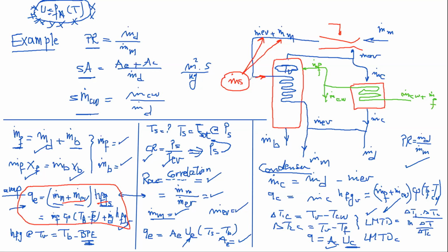It enters as saturated vapor, it leaves as saturated liquid. So the difference between them is basically HFG. Okay. Is that clear? But how do you equate it to MF times CP? I'm coming to that now. So it entered as saturated vapor and then it has lost its latent heat of condensation and leaves as a saturated liquid. So this is what happens to the steam.